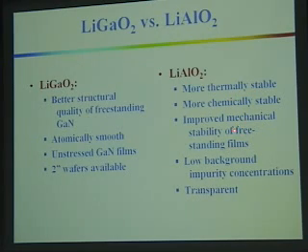It had improved mechanical stability in its freestanding forms. That is, we were able to get a lower stress state off the lithium aluminate. The background carrier concentration was lower in the material as well. And it was transparent, whereas the lithium gallate sometimes would have, we believe oxygen-related, yellow consistency to it.